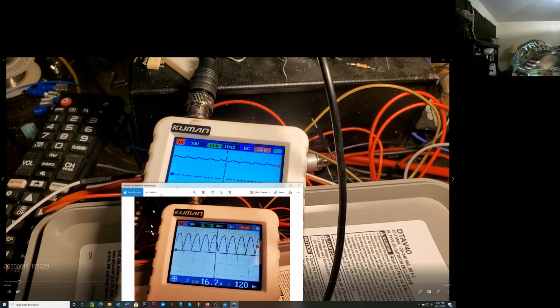So here's your sine waves going doot doot doot. This is the same thing, but it's the top. These peaks are these peaks. So once this drops down, the DC bus stays up here because of the capacitors, but because there's a load now, the load's going to draw the capacitor down. So it's going to follow the curve of the AC sine wave, and you're going to see where the sine wave was, and it's called a DC ripple.